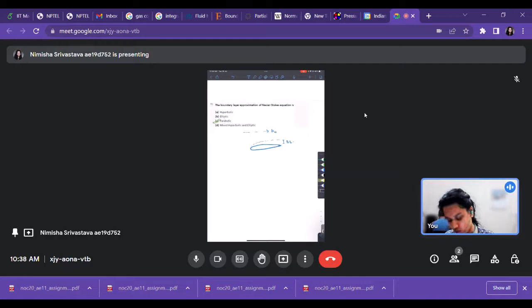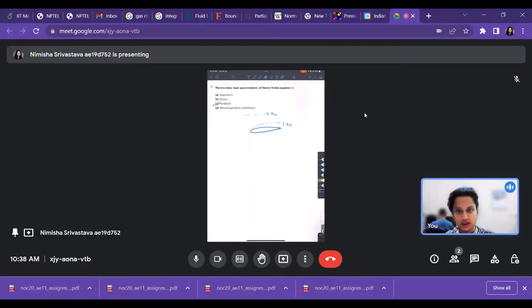Okay, so because of the reasons that I just mentioned, near the boundary layer, by using some typical magnitudes of u, v, the length and the width of the boundary layer, etc., we get a modified form of the Navier-Stokes equations at the boundary. So that looks like u du by dx plus v du by dy equals minus 1 by rho dp by dx. This is for the x momentum equation, so that we don't get confused.